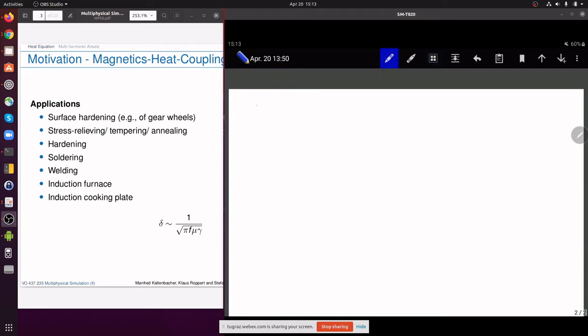So this C1 is based on classical eddy currents in your whole computational domain omega. So these are global losses that we will also consider as the main source of the dissipative power loss. So this is the main part of the heat source, scaling with frequency f.